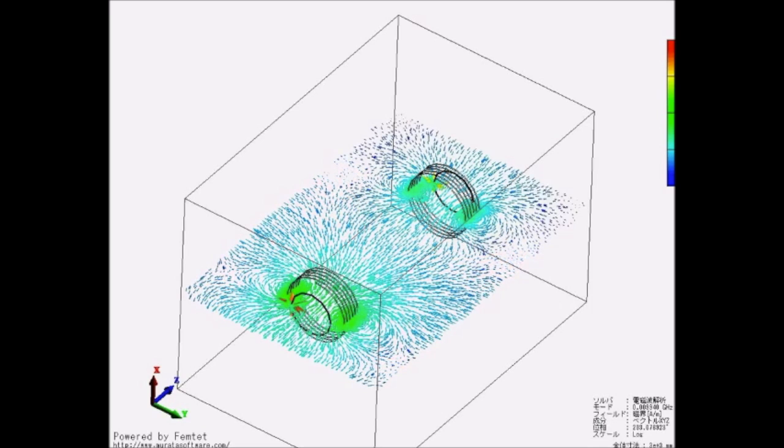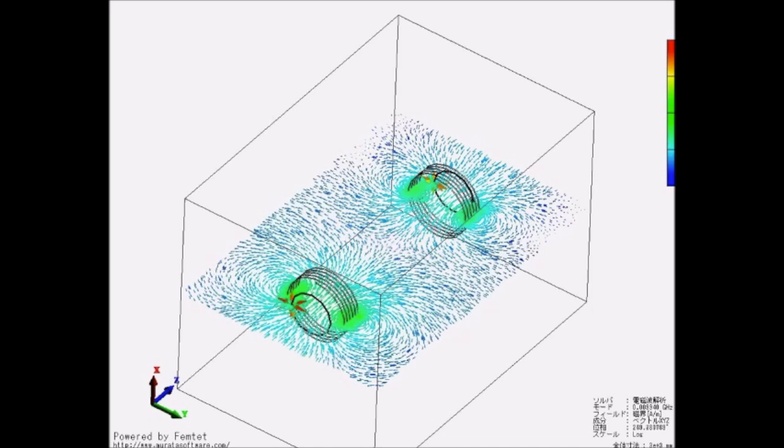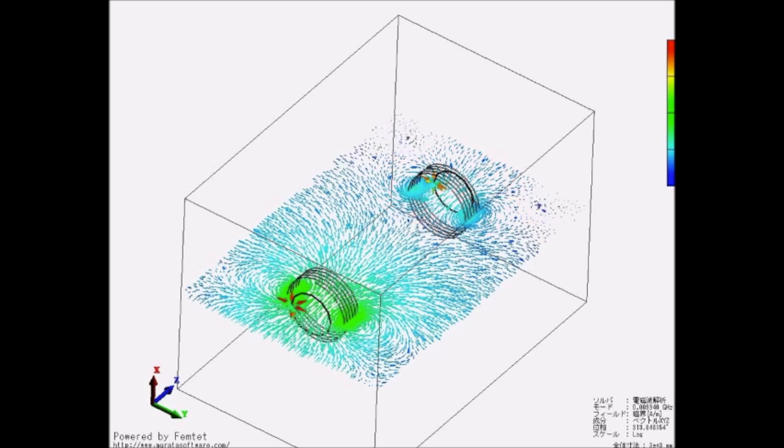The process whereby energy is transmitted between the transmitter and receiving coil is also referred to as magnetic or resonant coupling and is achieved by both coils resonating at the same frequency. Current flowing within the receiver coil is converted into direct current by the receiver circuit, which can then be used to power the device.